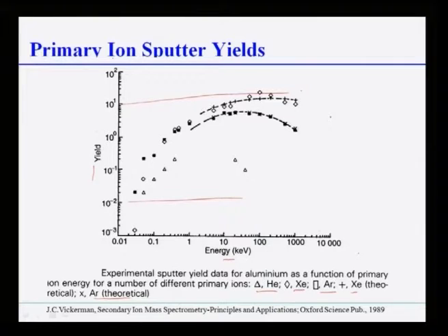So, as you see, as the energy increases, sputtering yield increases. Normally we can use from 10 to 100, 150, 200 electron volts as the energy. Sometimes people use 3 to 10 also. This is also not bad. In this window also you have something like 5 to 6 secondary ions per unit primary ion that can be created.